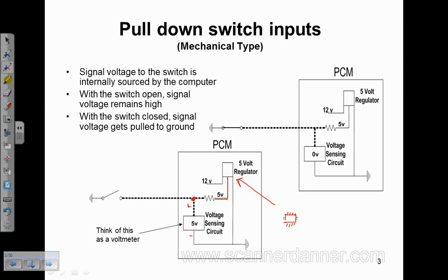So a little bit of some laws apply with voltage and voltage drops, and one of them being, well, we have a resistor right here, so resistors are going to drop voltage, correct? But we need to have current flow for that to take place. So right now, there is no current flow in the circuit. That voltage can't go anywhere. That voltage sensing circuit is not a path. And so that whole leg of this circuit reads 5 volts right now. This is if you were out here with a voltmeter to ground, you would read 5 volts on this circuit with the switch in that position.